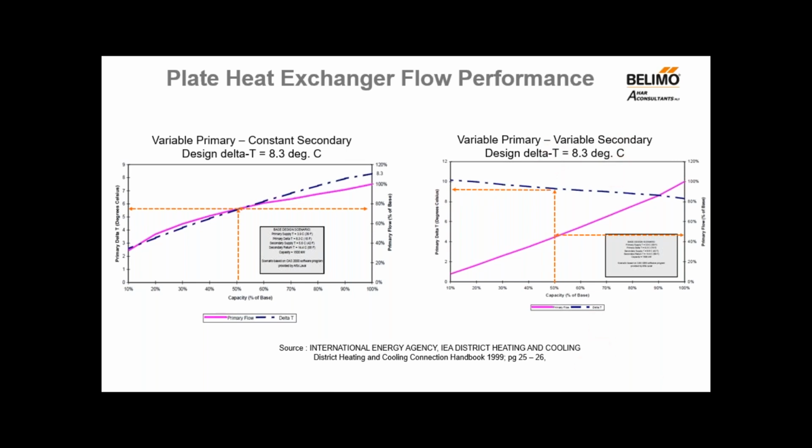So, primary control valves are one of the most important single elements in the interface with the district cooling system, and proper valve adjustment and calibration will save you energy. High quality industrial grade control valves should be selected for more precise control, longer service life, and minimum maintenance. Variable flow on both sides of the heat exchanger is required in order to maintain a high system delta T at all load conditions.